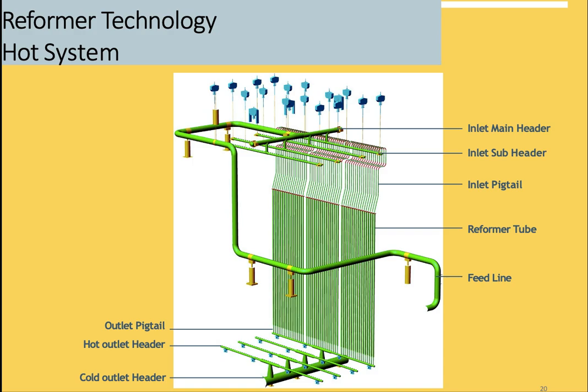Okay, the corrective action is to reduce the load. You have to reduce the load and increase the steam ratio for sure. Plan to make decoking or catalyst replacement. Check the feed contaminants.